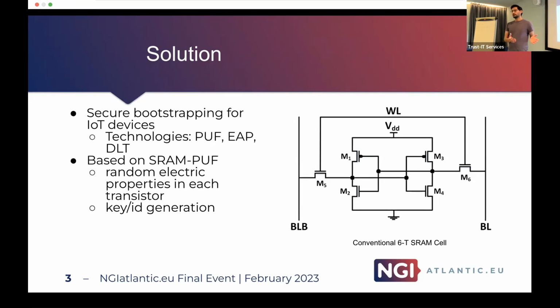In this project, Ashwin worked on a proof of concept, physical unclonable functions. What it means is that during the IC fabrication and manufacturing process, some kind of noise and variation occur in each chip. In the proof of concept, these variations can be utilized to generate unique identification and unique keys for communication. There are multiple ways this proof of concept works, multiple techniques. And one of the techniques that we used was based on SRAM.